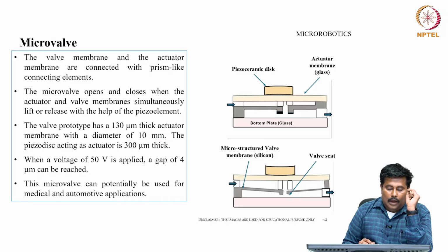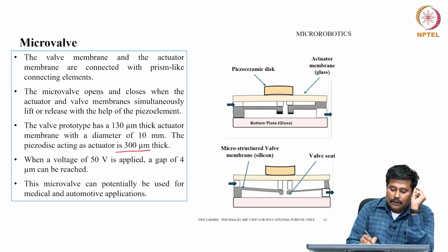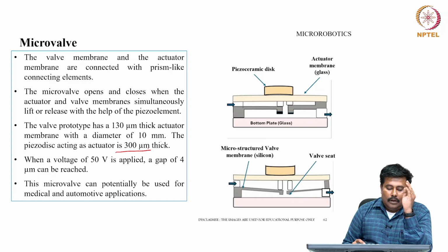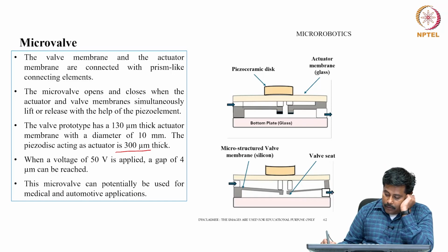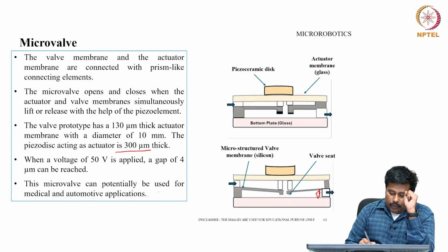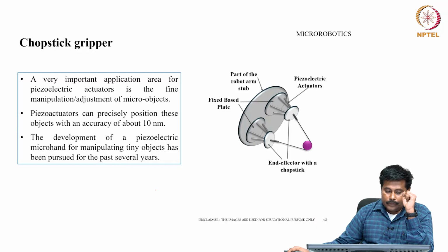The valve prototype has a 130 micrometer thick actuator membrane with an inner diameter of 10 mm, and the piezo disc acting as an actuator has a thickness of 300 micrometer. When a voltage of 50 volt is applied, a gap of 4 micrometer can be reached, and these micro valves have potential application towards drug delivery and automotive related applications.